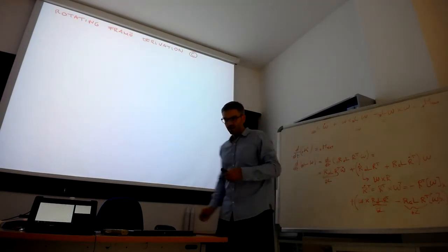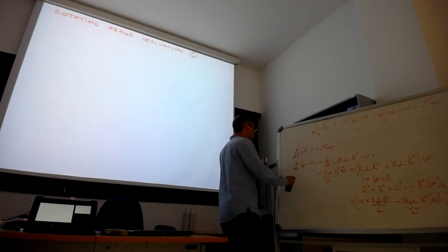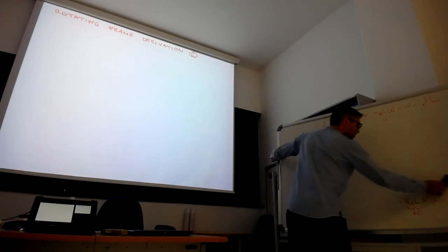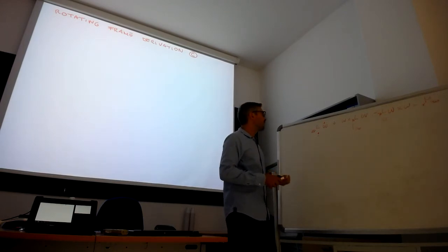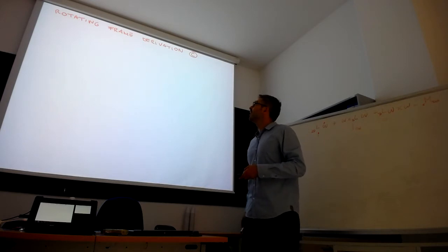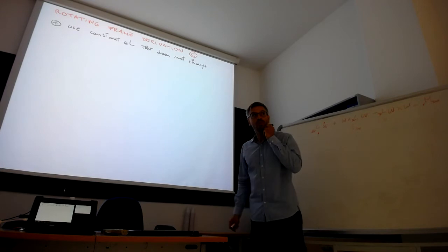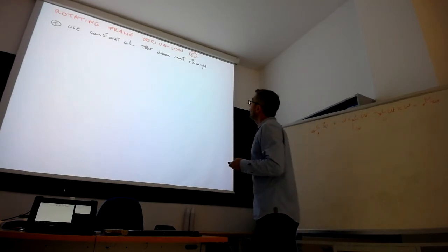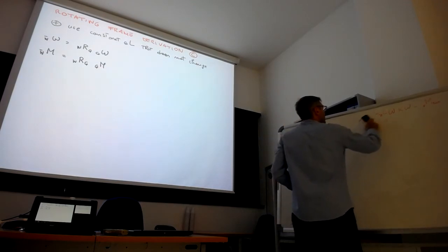But let's see. We said that we have this inertia that is changing with time. This means that if we use it in an optimization and we are writing symbolic equations, it will take a lot of time to deal with that, because we're going to have rotation matrices in there, which are cosine and sine, so there is some nonlinearity there. If we would like to use, for example, the constant inertia expressed at the central mass, or even at another point of the body, like the base frame or whatever other point is constant, such that it doesn't change, we can see what we should do to formulate this equation in a rotating frame.